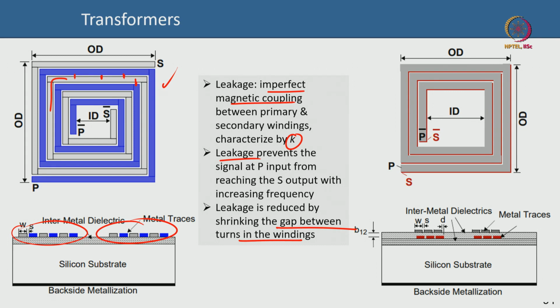In vertical coupling you will only see one coil because there is another running exactly below that. You can see in the cross section here there is one top set of coil and then there is a bottom set of coil, they are separated by the dielectric. But you need to take the bottom coil also appropriately out so that you can probe them, connect them or hook them up to whatever you want.